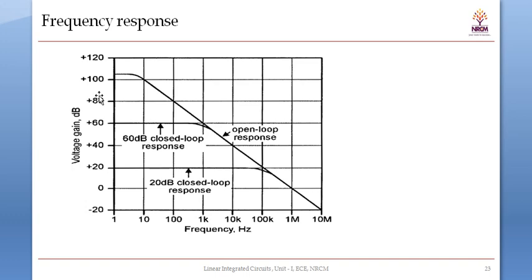So generally first generation op amps are going to require an external compensating network. So you are attaching the resistors and capacitors outside the op amp in the first generation, but from the later generation the internal compensating networks are manufactured or fabricated inside the IC. So this is about your compensating network and the frequency response.